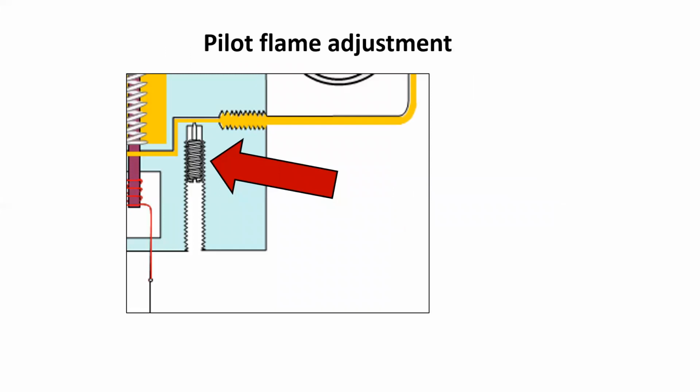Finally, why would you want to do that? Well, if you're not getting 30 millivolts DC, it's probably one of two different situations. One could be that the thermocouple is bad and it needs to be replaced. The second could simply be the amount of heat applied to the thermocouple. If the pilot flame is too small, it won't have enough heat to heat up the thermocouple to a point where we get the rated 30 millivolt DC value.